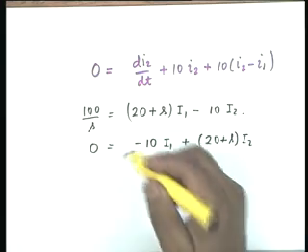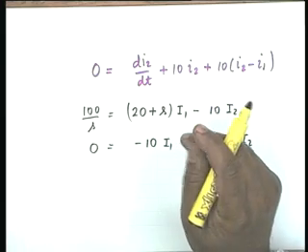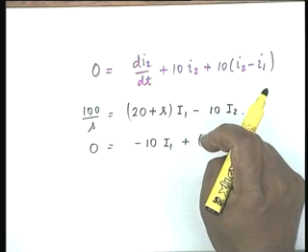Now you have a choice. You can go to the time domain. You can find the natural frequencies, write down the corresponding equations, and then make your life miserable by finding I1(0+) and I2(0+). You have to find them out. So one, the characteristic equation we can write here.